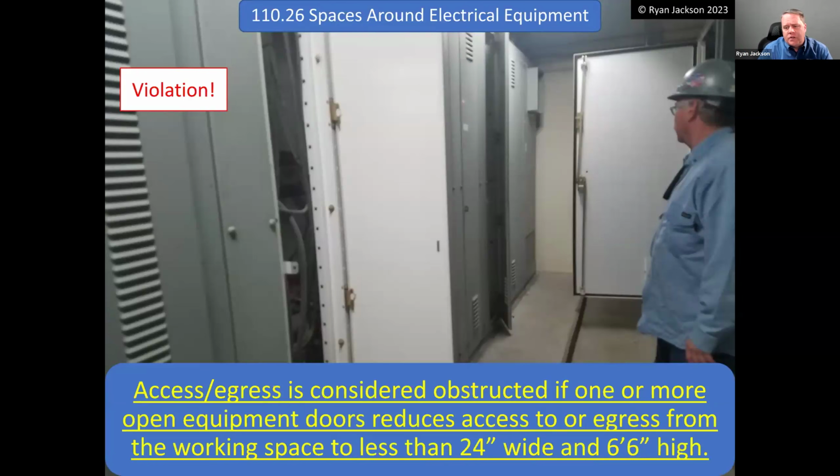Access/egress is considered obstructed if one or more open equipment doors reduces access to or egress from the working space to less than 2 feet wide and 6.5 feet high. So looking at this picture, we're going to have to measure with both of those doors open. And I've got to have those doors miss each other plus 2 more feet.